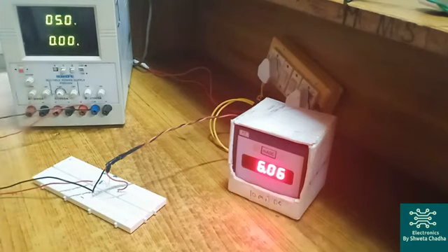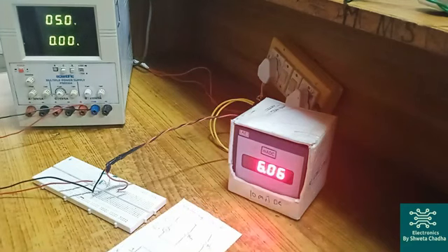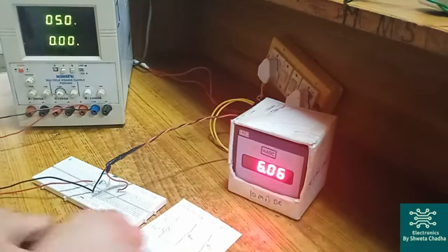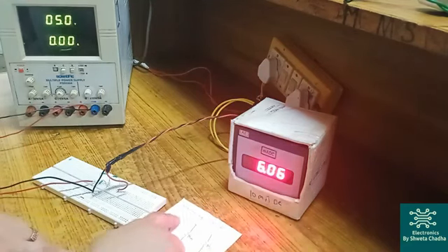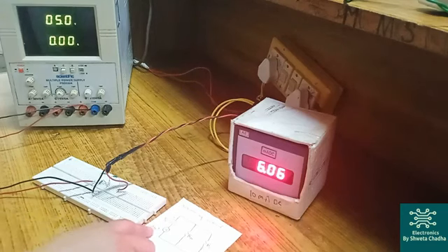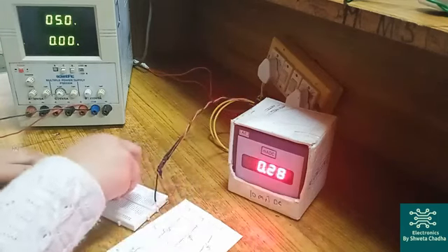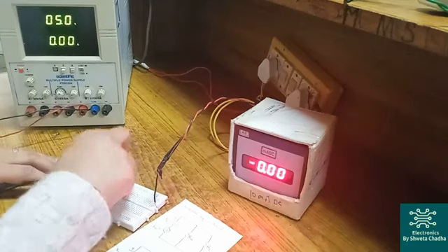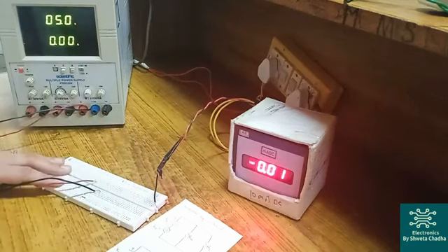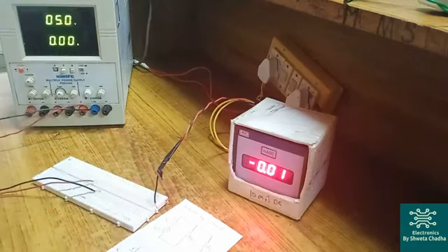Now regarding this fourth step, let me just show you the circuit diagram. Instead of current source, we are going to use supply in series with ammeter so as to adjust how much voltage is sufficient for IN. So let us design this first circuit diagram. For that we require Rn. So Rn is our 330 ohm, this one. So you can have a look.